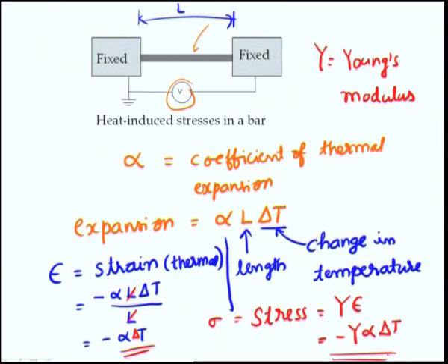So, we get the thermally induced stress. Now, when it is hot, let us say we lay down another material on top of this. If that new material and this material have different thermal expansion coefficients, then the stress will remain in both the structures even after they are brought back to the original temperature. To see this, let us say we have one layer with a certain expansion coefficient, and on top of it we put another layer with a different thermal expansion coefficient.